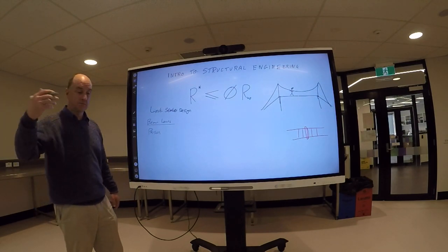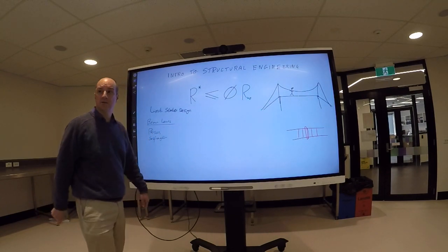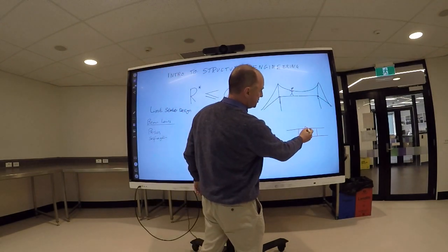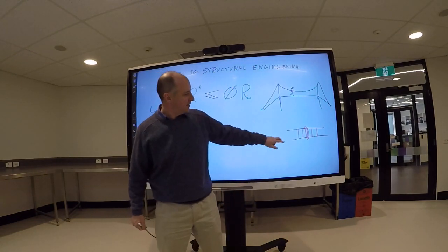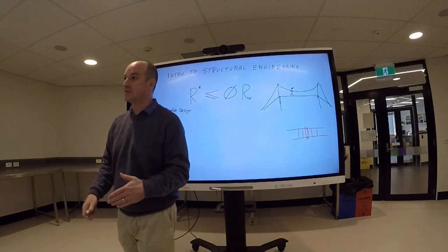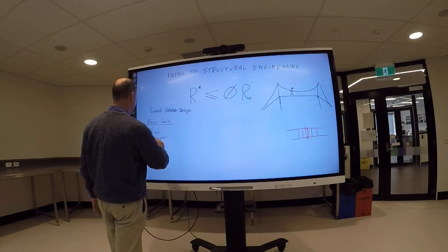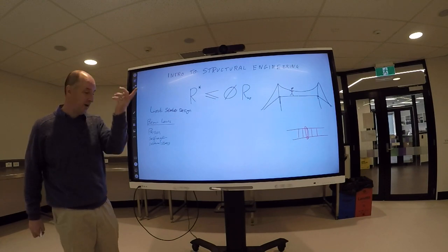The dead load. Yep, let's call that self-weight. Any other loads? It's connecting the two edges together. So what I hear you say is that perhaps this one was made a bit long and that one was made a bit short. There's a fabrication internal stress in there. Let's go with that. That's what you meant. Yeah. Internal stress. Yeah, others? It's gone over something, so there's room for the wind to go. Wind load. Yep.